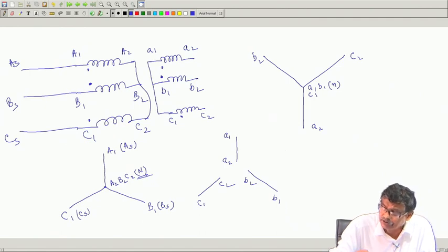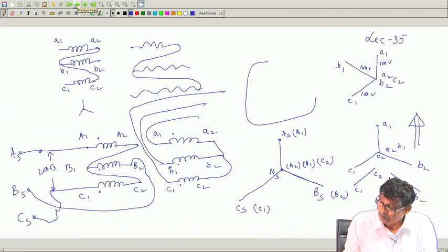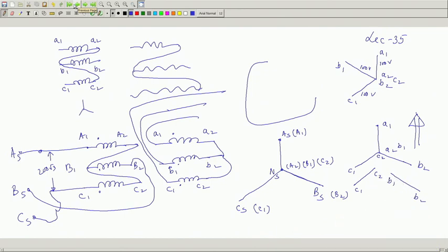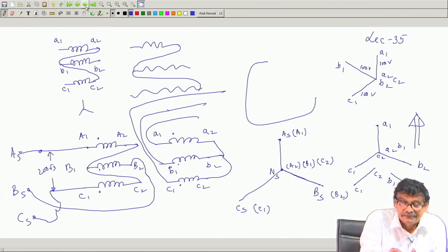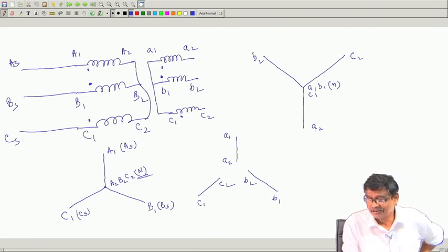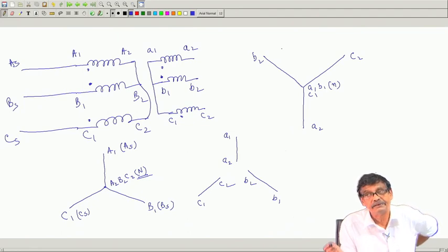If it is A2 B2 C2, in the earlier case there was a mix up, although you would get a balanced 3 phase there, but it is A1, it is B2 C1. Technically correct, I mean it will work, but the point is I should be very systematic in doing that, so that things are standardized. Here is also no mix up, A2 B2 C2, balanced 3 phase sequence is ABC like that.